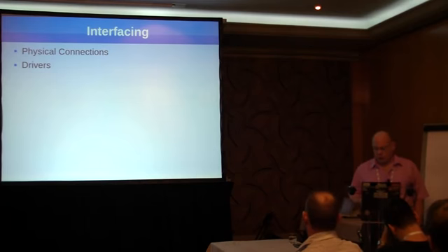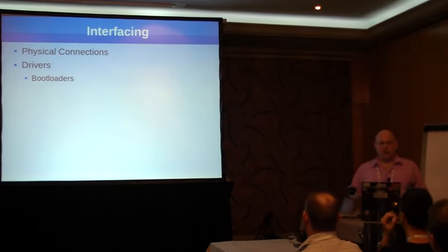devices such as U-Boot and bootloaders. Because I2C is extremely easy to set up, and most I2C controllers on SoCs are extremely easy to work with, having it supported in a bootloader is very easy to get initial support. Now, once it's booted with your bootloader, you can actually read from the I2C controller and talk to serial EEPROMs or other devices to get information.